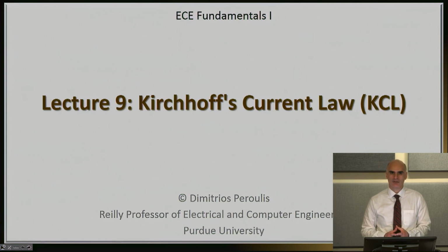It's important because those laws, strictly speaking, apply only for DC circuits, only when we have a constant voltage and a constant current. When the current starts becoming AC, starts alternating, those laws, strictly speaking, are not correct. However, in most practical situations, they are extremely good approximations, and we will still keep using them until the frequency of the alternating current is so high that those approximations truly break down and we can't use them. So keep those disclaimers in mind, and let's go ahead and study Kirchhoff's current law.